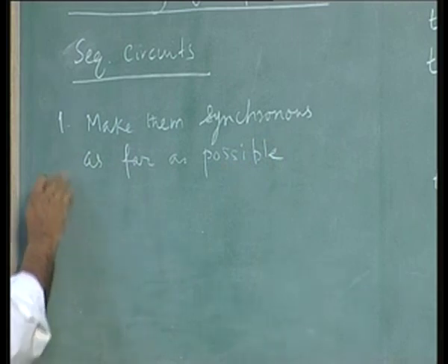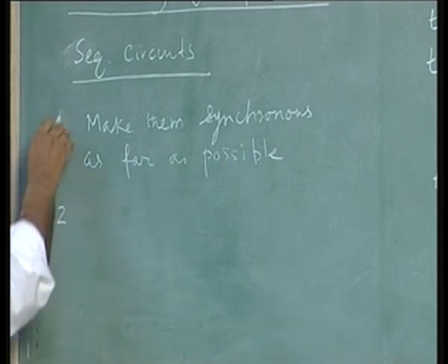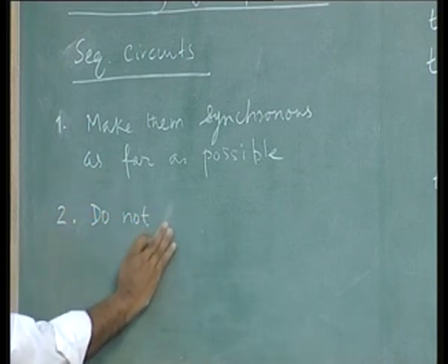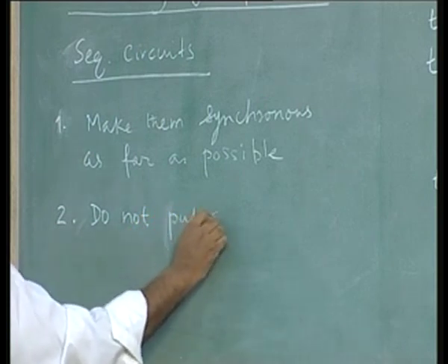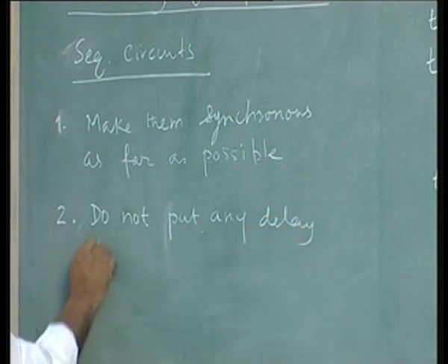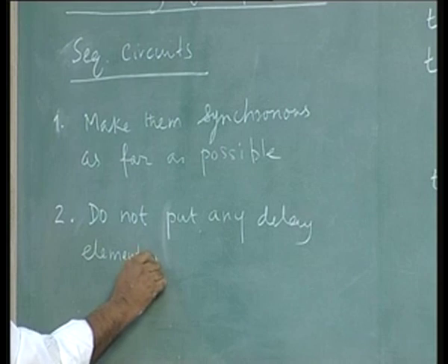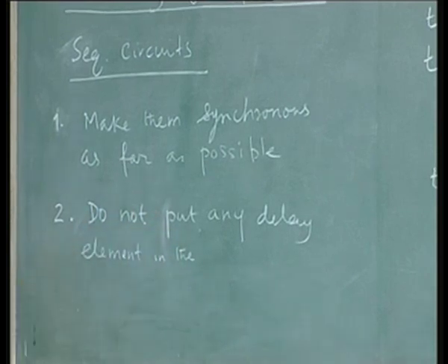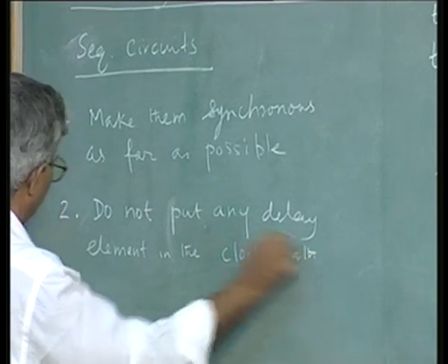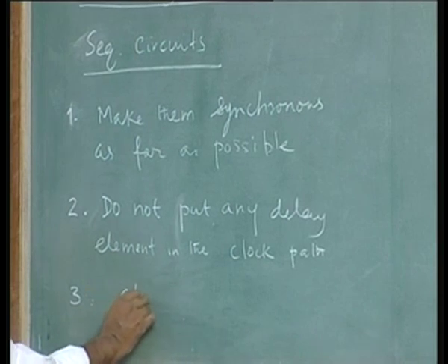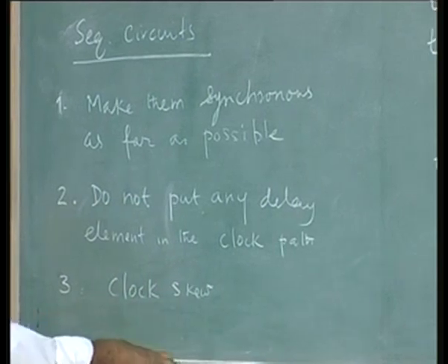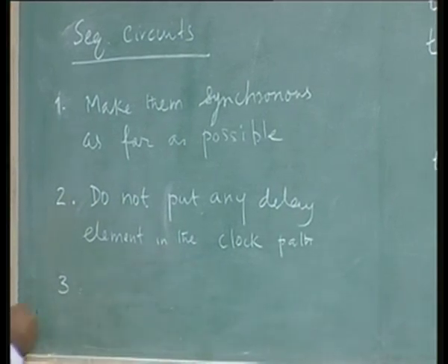Two, do not put any delay element in the clock path. Three, I said clock skew, avoid clock skew. Clock skew can be part of this.